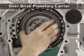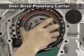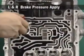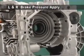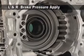When overdrive planetary carrier is rotated from rear cover's side after it is assembled, the direction has to be counterclockwise. Apply the air pressure to the hole of low and reverse brake of the valve body side transaxle case to separate the low and reverse brake piston.